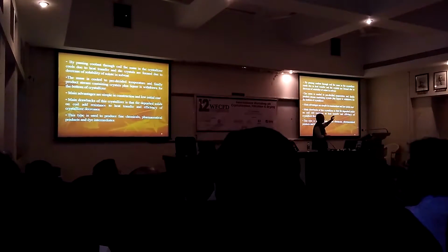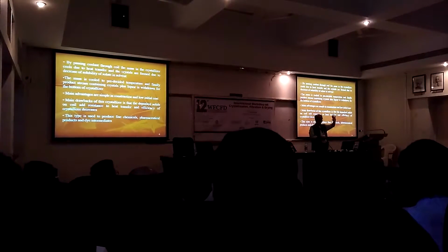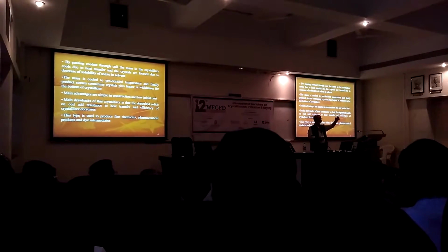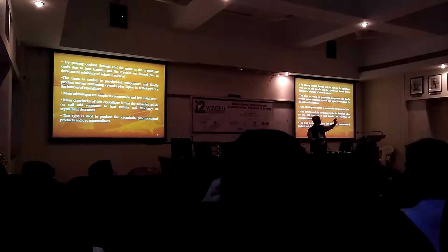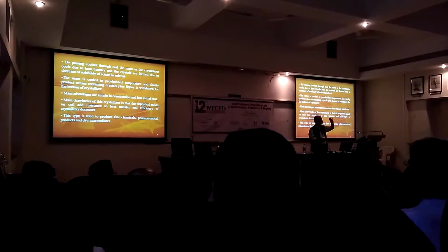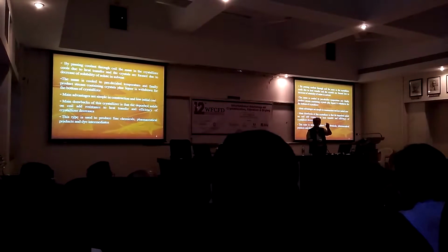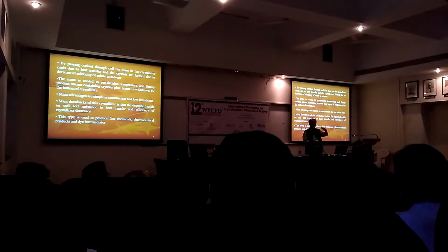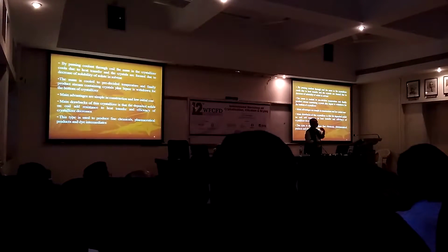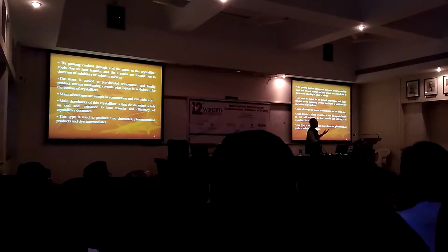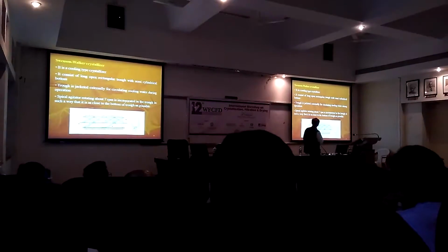So essentially any crystallizer will require a mechanism by which you can keep the solid particles in suspension, offering all the surfaces for the deposition of the solute. And a second mechanism is to transfer heat to the material which is inside, either remove heat or supply heat, depending upon whether it is a cooling type of crystallizer or an evaporative type of crystallizer.